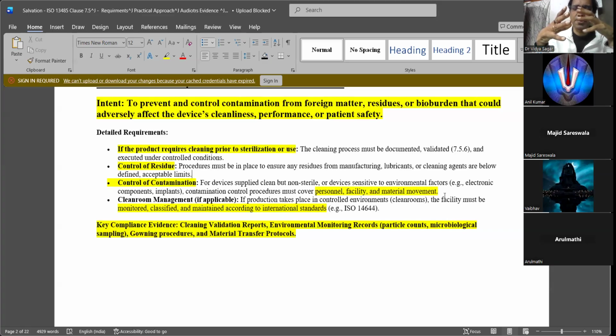If you are not cleaning properly, since it is a clean room, there is a chance for particulate matter to recirculate, though you have a very perfect HVAC system. Air handling units, 7 cycles or 10 cycles per hour. The HVAC could be perfect, with all the air filters and all that.